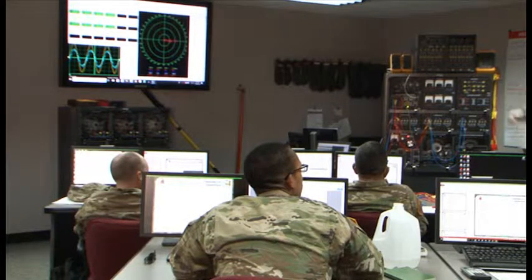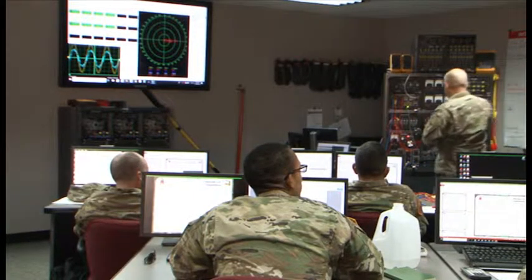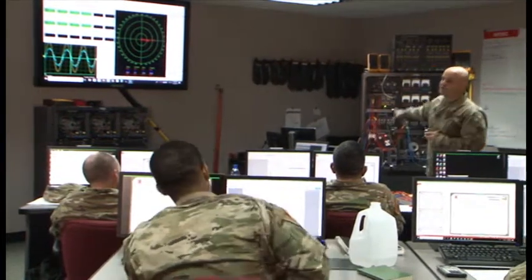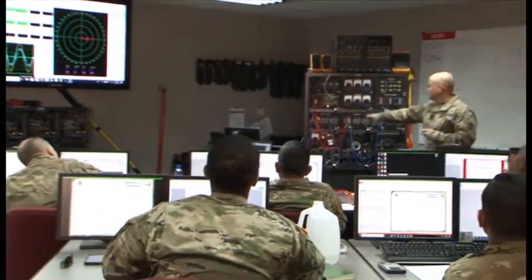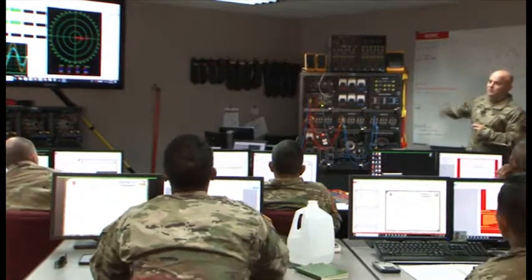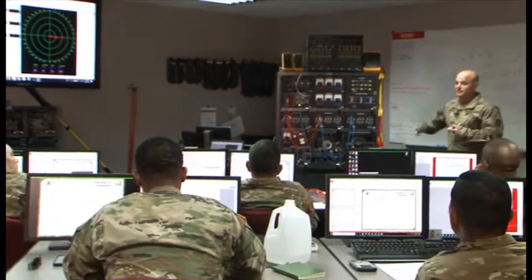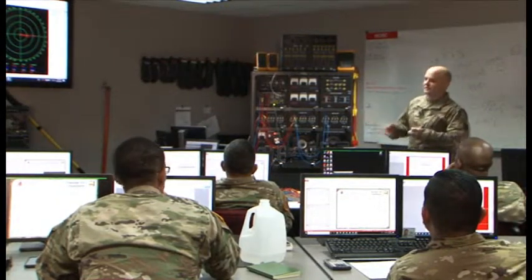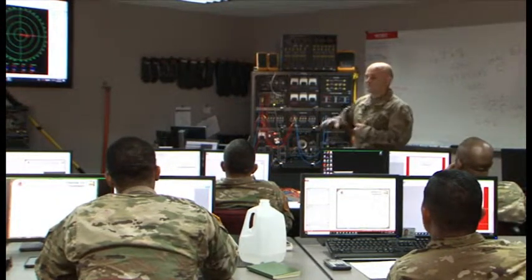Here I'm just looking at source. So you're seeing directly how the system responds, and by system we could take this and change this to, we could say that this is the generator, right? And now we're measuring what the generator sees, even though out here we've got this stuff going on at the load, right? And the load is moving us inductive. We've got motors and transformers out there and all kinds of stuff. This inductance is happening, but it's getting a little intense.